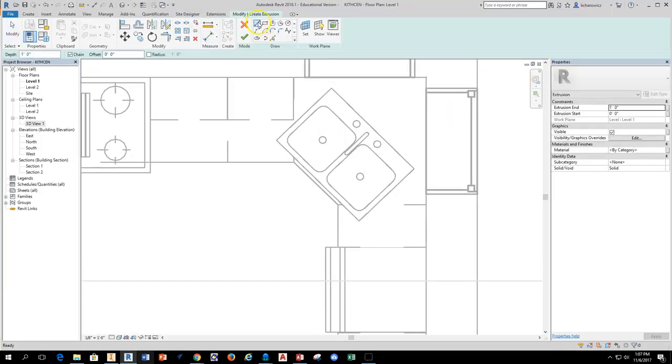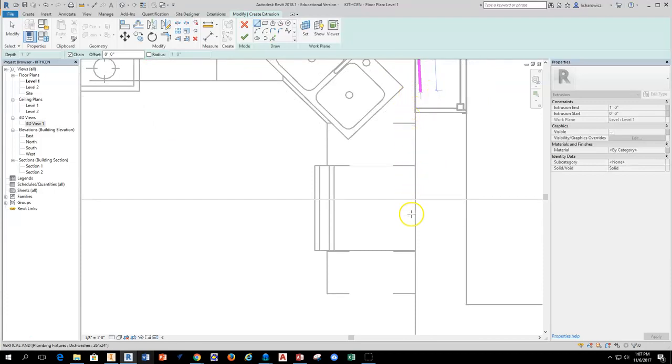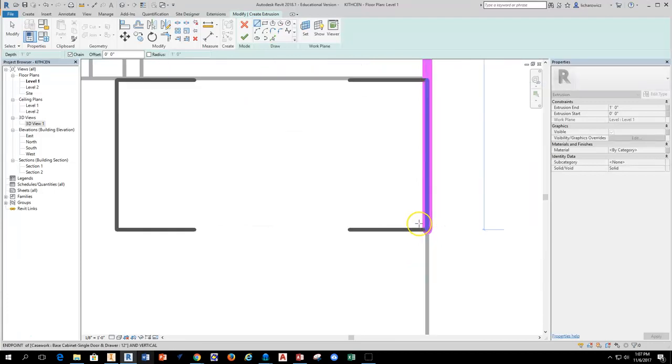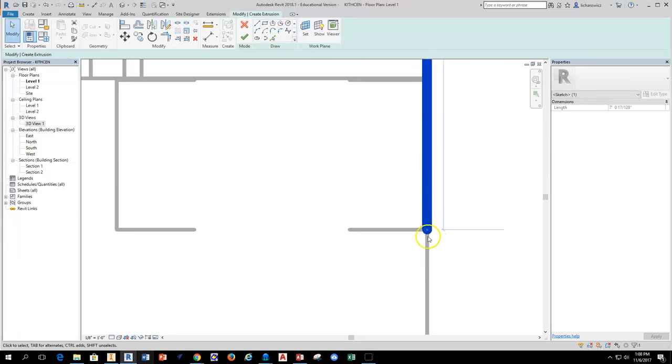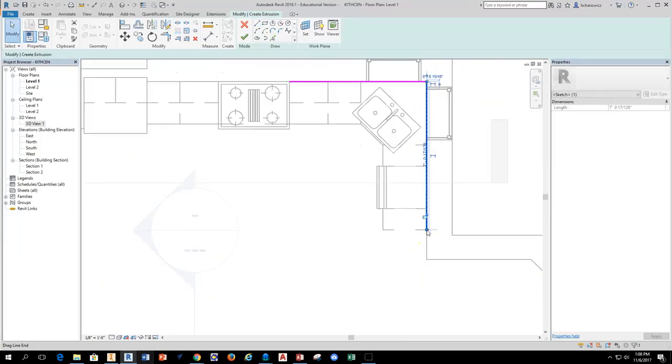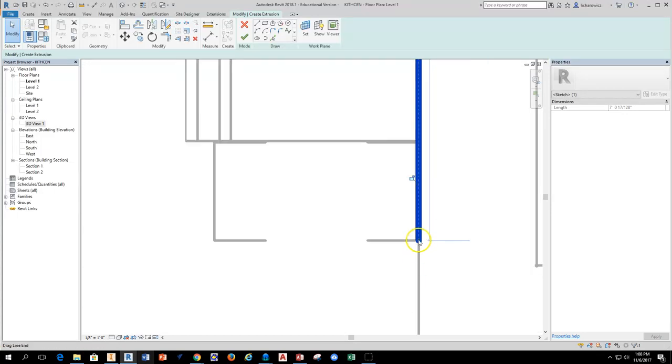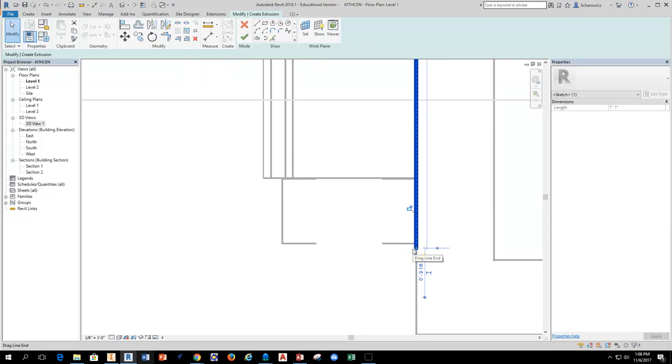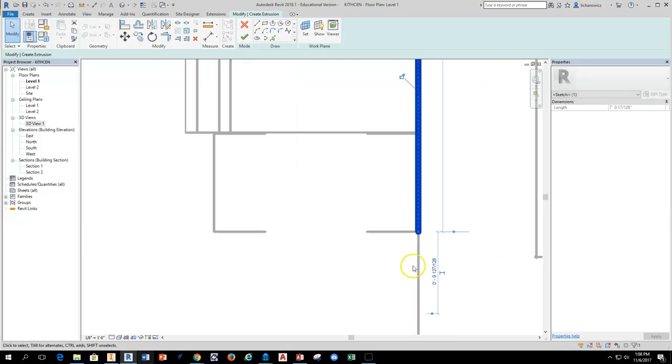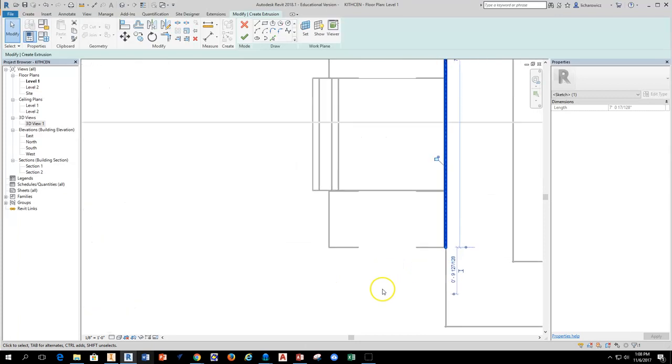I'm going to grab my line tool and trace the back of the countertop, which is going to run directly against those walls. My countertop is going to run all the way to the end of that cabinet. I'm going to hit escape twice, and then extend this just slightly past the edge of this cabinet, because the countertop should overhang by approximately 1 inch to 1.5 inches. But given that this is an end panel, I'm not going to do that. End panels should generally be flush. I'm not sure if there's going to be something else going in here.